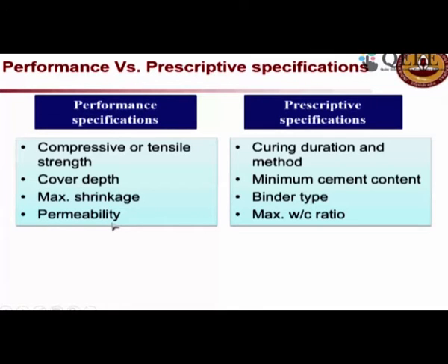So here we can say performance: you put this cover depth as a, and after the construction is over, there is now technology available to measure the cover depth without even opening the concrete. You can do some non-destructive testing and find the cover depth. We can also specify something on shrinkage. After about a month or 28 days, or even a couple of months, we can say that concrete should not have this much shrinkage, otherwise you will have shrinkage related issues.